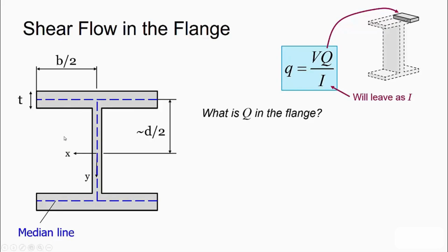So on the left here, just so that I don't have to play around with negative signs in my x variable, I will specify a section point, a distance x away from the center of the web, and that will define this green area, which is equivalent to this small area sectioned away.